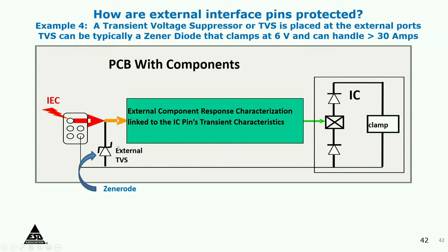All those Zener clamps, even at currents of 30 amps, the Zener voltage builds up. Although it triggers at 5 or 7 volts, it goes up to 30, 40 volts. If it is at 40 volts, depending on the source impedance at this point, you can still get a significant amount of current going in. So how do you mitigate it? You mitigate it by putting inductors, capacitors, filters, all kinds of things, and all these filters have to be able to handle the USB high frequency. So this is a very complex thing of protecting the whole chip.